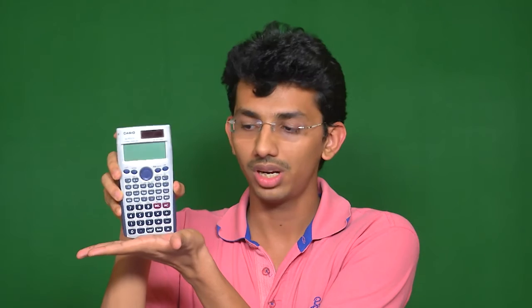Suppose this is my non-structural element, say an Almirah. In the first case, sliding, it will go like this. If this is happening, we identify it as sliding. Second is rocking behavior, where the object will not slide but will rock at one of its sides. And third, in case of excessive rocking, it will topple. So these are the three failures, and we will check the safety of the non-structural element against them.